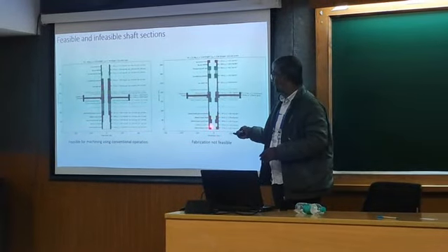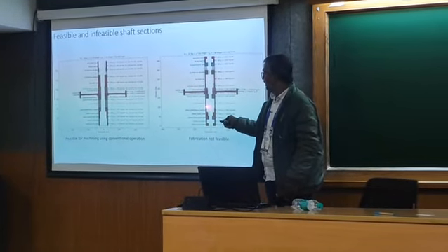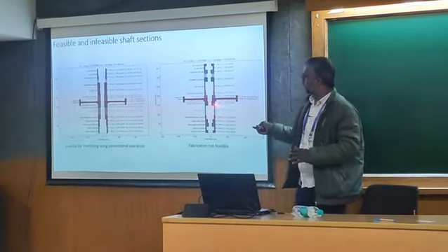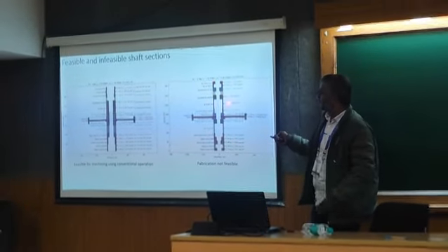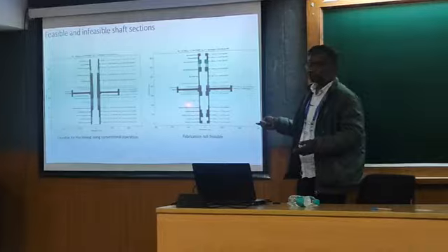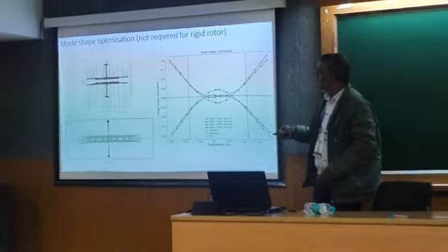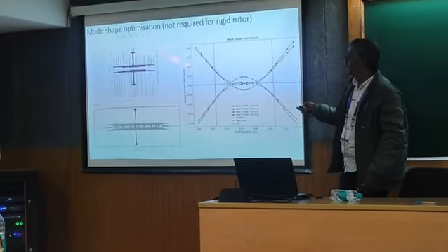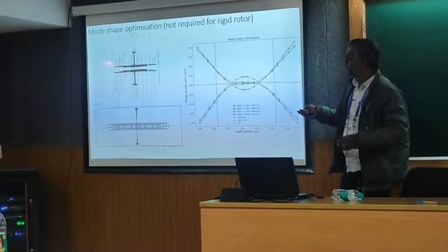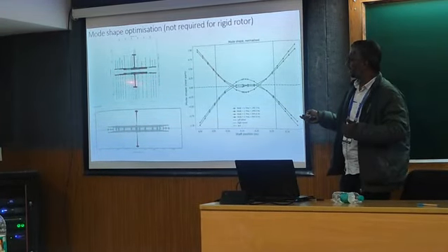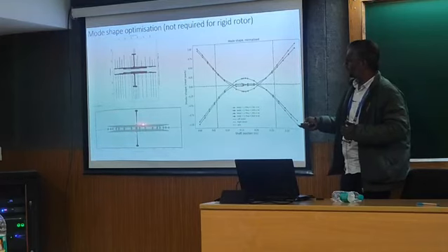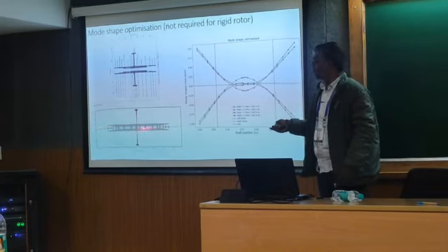Shaft is optimal, but this section needs undercut of the boring tool. So these designs we are avoiding when optimizing. And also we are checking the mode shapes of the rotor for each design iteration. For that we are using the tool RotFem. It is an open source tool.